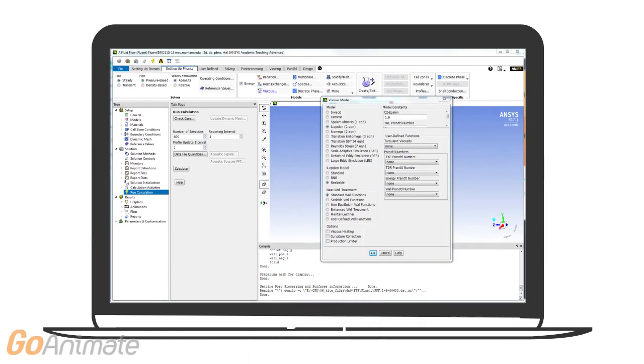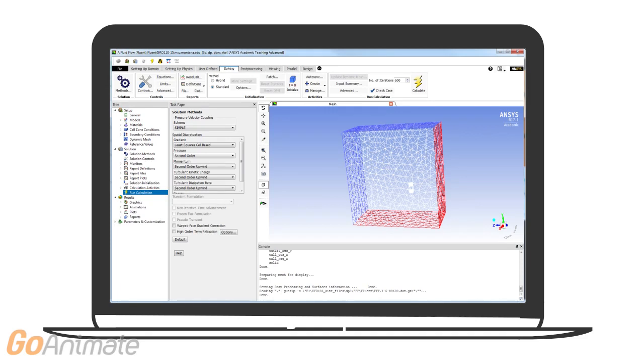In Fluent, the steady, pressure-based solver was used because the 10 meter per second wind velocity used for the analysis is slow enough to warrant an incompressible solver. The K-epsilon turbulence model was used because it is a good model for flow over complex geometries that have normal pressure gradients. The consistent, SIMPLE solution method was used for the analysis.